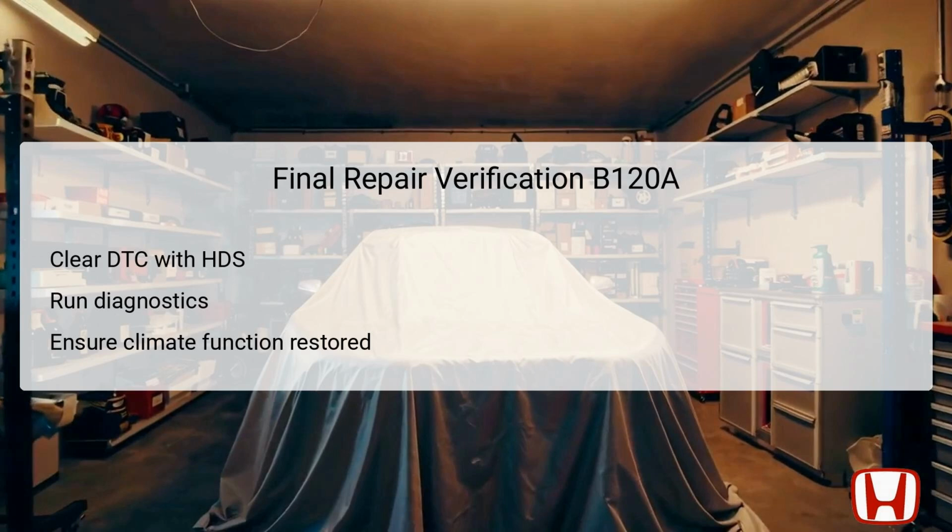After completing all necessary repairs and troubleshooting steps, the final repair verification is crucial to ensure that the DTC B120A is no longer present. Begin by clearing the DTC with the HDS to reset the system. Once cleared, conduct further diagnostics through the HDS to verify that the climate control functions are restored.